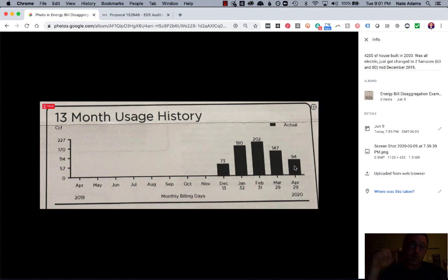This was really hard, and very strange, that the cooling load and the heating load were almost identical on this house. I haven't seen that before, and I don't know when I will ever see it again, because it's almost always 2 to 1 heating to cooling here. So if you've got a 20,000 BTU cooling load in Cleveland, you probably have a 40,000 BTU heating load. So that was very unusual.